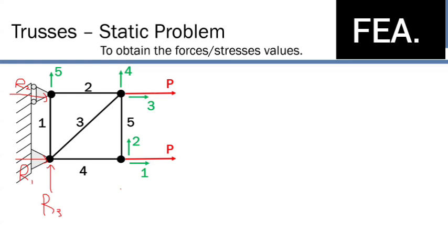However, if you pay attention here, you'll see that all of our external forces are in the x direction, right? So the system doesn't actually want to exert a higher reaction force than it needs to. So if all the forces are in the x, all of our reaction forces are also going to be restricted in the x direction. It's not going to work more than it needs to. It's just going to do exactly what it needs to restrict external motion.